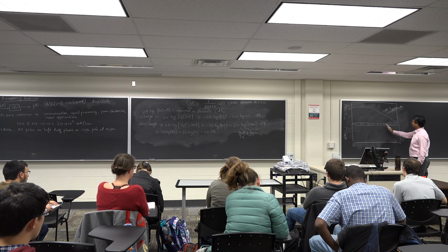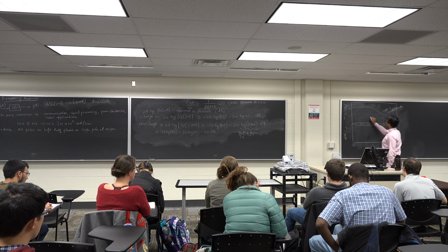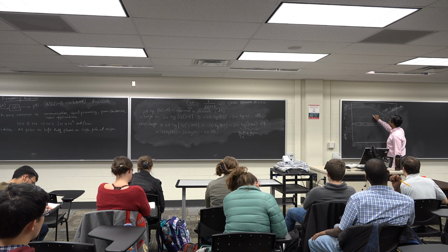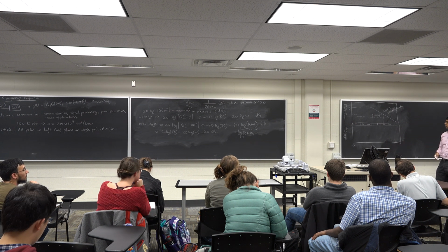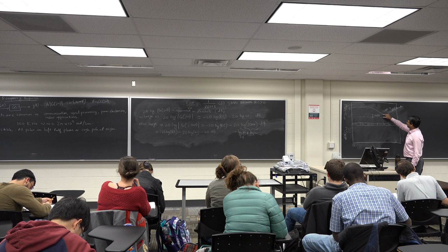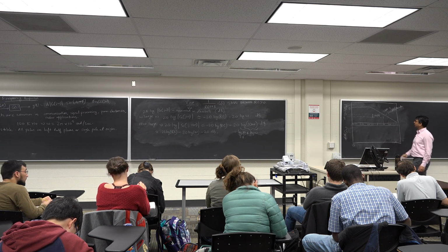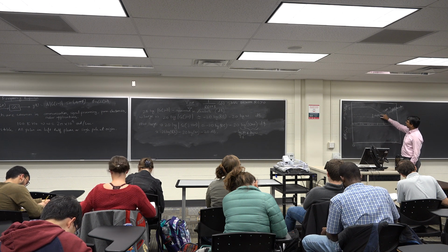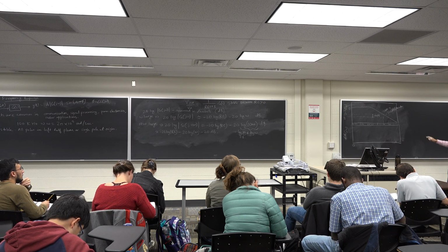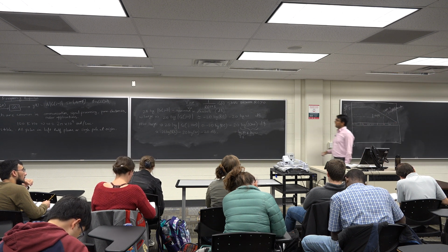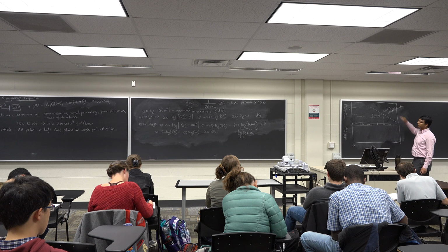So the slope of this line going from 10 to 100, let's say this is my value at 10, this is my value at 100, and this difference is minus 20 dB, and this is a decade. A decade means I multiply the frequency by 10, and the slope is the reduction in y-axis versus the x-axis. So in x-axis I'm looking at 1 decade, at y-axis I'm seeing a reduction of minus 20 dB. So that's why the slope is minus 20 dB per decade. And that's a characteristic of a first order system. So whenever you have a first order system like this, you will always see this slope of minus 20 dB per decade.